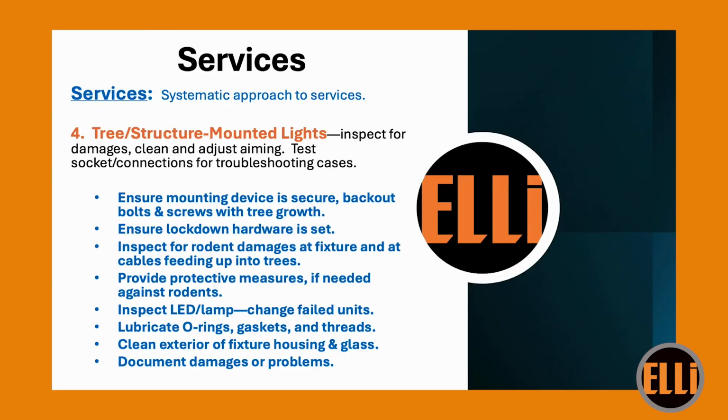So spend as little time on the ladder as you can and ensure your ladder is stable wherever you've located it. So again, let's go through our bullet points. It's more or less the same, but I'll just run through them real quick. Ensure that the mounting device, your hardware, whether it's a single hanger bolt or 3 hanger bolts or whatever your means of attachment from the light fixture to the tree or the structure, make sure that that's stable and secure.